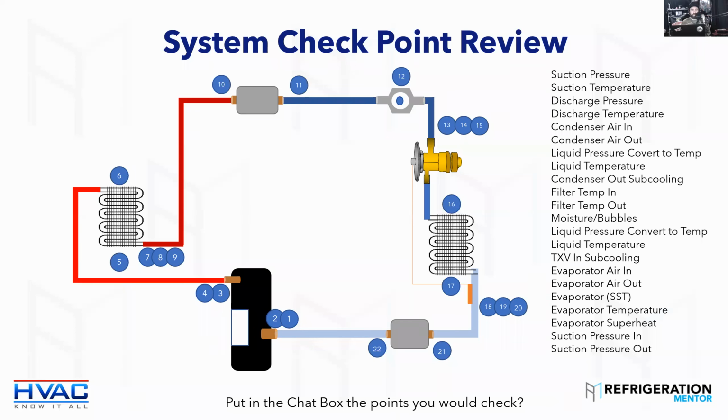And it's fine right now. And if it gets to the point where it needs to come out, 100% it'll come out. It's just been one of those things where I know you probably see suction dryers in units for like 20 years that no one's ever come and taken out. But I know what you're saying, Trevor, that a lot of manufacturers say that after the system's been cleaned up, you should go back and remove it.